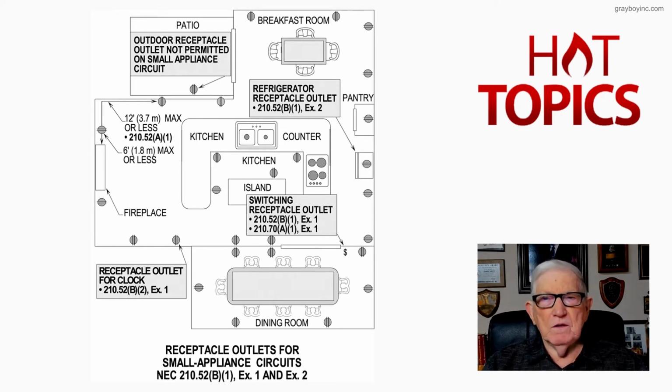However you want to do it, you're just consistent with it so that they're evenly spaced horizontally, and look good, like a good installation should. And then notice the receptacle outlet over here that you see at the bottom. The exception there says if it's over 5 foot 6 inches from the floor, then it's not a required outlet. You'd have to put another outlet in if it was necessary, if you didn't have 6 foot between the other two outlets, say, in the center. So that's a good way to look at that.